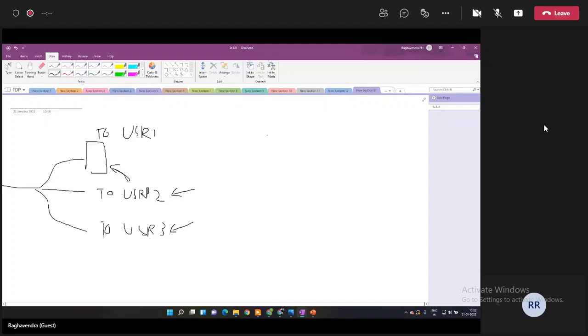And it's not always best, since the person who's working on this might not have expertise with respect to the physical aspects of the FPGA. Maybe they're very good with VHDL, but they're not very good at figuring out which output they have to take it out at, how they're supposed to synchronize it, all of that. So that might become an issue, and it's best not to tinker with it on a hardware level. It's okay if we do it at a software level, but especially on a USRP FPGA card, the inputs and outputs are predefined, and it's usually best not to tinker with it.